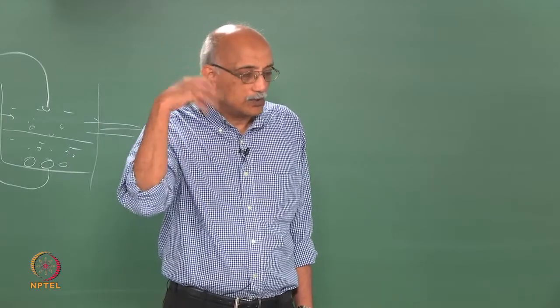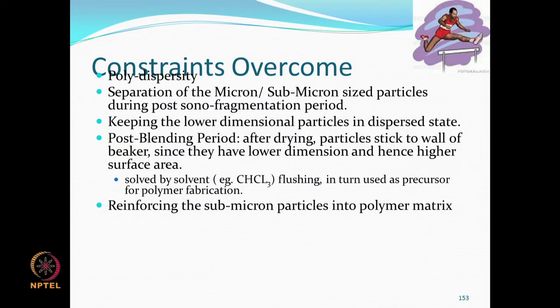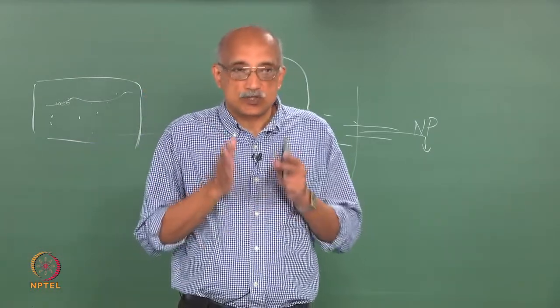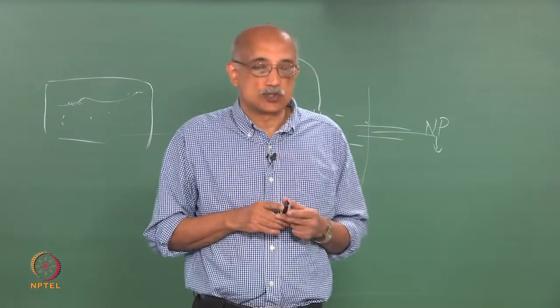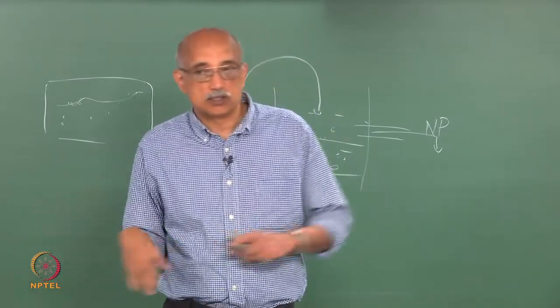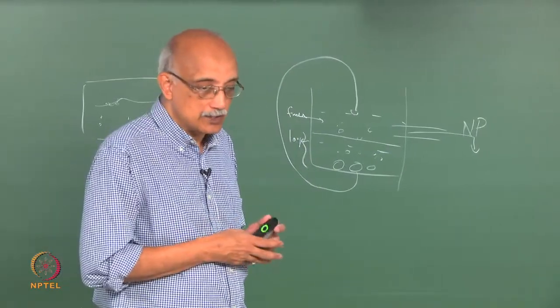So you know, this whole mechanical operation of nanoparticle synthesis and nanoparticle dispersion using an acoustic field is a very promising and challenging field, but there are certain challenges that you need to overcome. The first is what we call polydispersity. Not all particles that you feed in are of the same size, and any process that you use depends on how spread out the feed particle distribution is. So if you start with a very tight size distribution of the feeder particles, then you can achieve much better functional results. But if the distribution broadens, then the effectiveness of the nanoparticles will decrease.